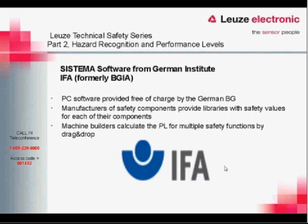One resource we can also use is SISTEMA software. This is software provided free of charge by the German BG. Manufacturers of safety components can provide a library with the safety values for each of their components. So basically, you would get this from ourselves, Leuze, or any other safety device company. They can give you this library, and it has all the values for each of these machines. Then you would just drag and drop and put a circuit together, and it gives you a yes or no indication once you put everything together: yes, this meets the performance level you're looking for, or no, it does not.